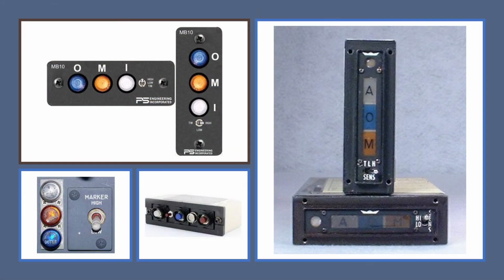Marker beacon interception is relayed to the pilot on the instrument panel. There are several different configurations for the instruments, but the color readings are standardized to blue for the outer marker, yellow for middle, and white for the inner marker.